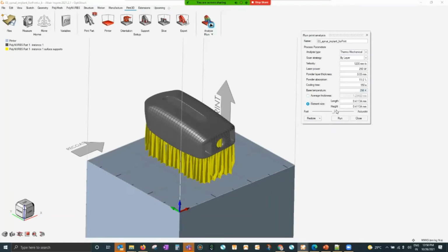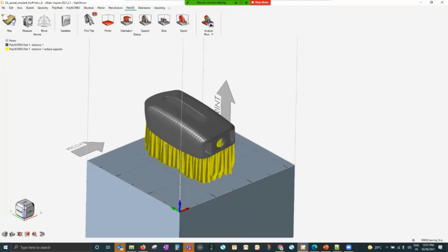And then you have a simulation speed versus accuracy slider. So you can say it is fast versus accurate, so that you can play with. When you want a very accurate result, or rather the result is to be compared with something, then you go ahead with accurate. If you are in the initial stage, just want to see the behavior, you can just go for fast. Irrespective of fast and accurate, the simulation will take a little longer time, maybe 15-20 minutes. So we'll not spend time over here. What I'll do is I'll just show you the result over here.